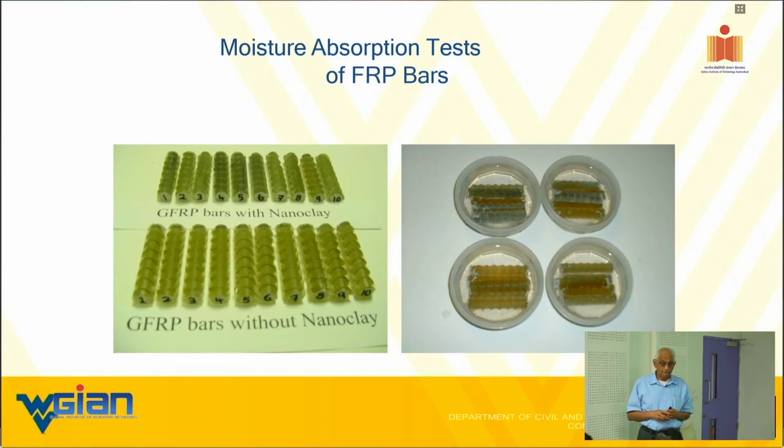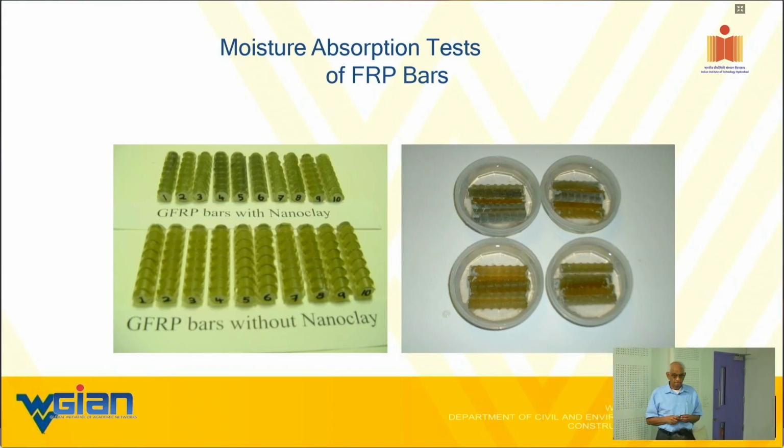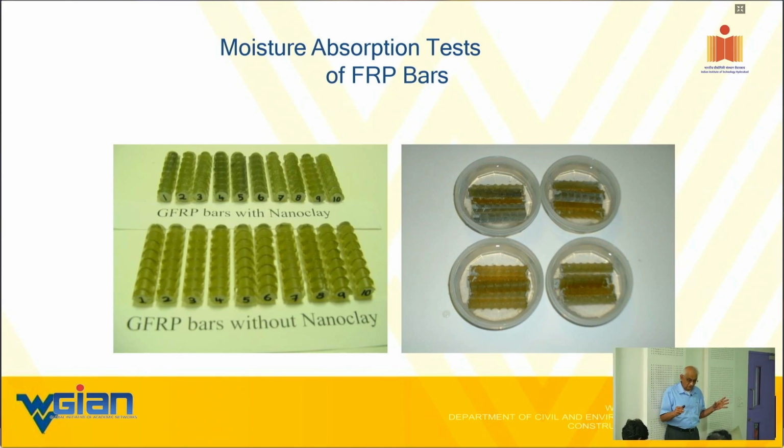But the thing is, the void percentage will influence the strength of the material. Oh yeah, it does, so we have to be careful about it. That is why I said an intercalated nano clay, if it is not properly dispersed and exfoliated, gives me a bigger problem. You have to have a very uniform dispersion. I didn't show here, but I have a number of SEM plots where it is not dispersing well enough, then obviously that shows up in your results.